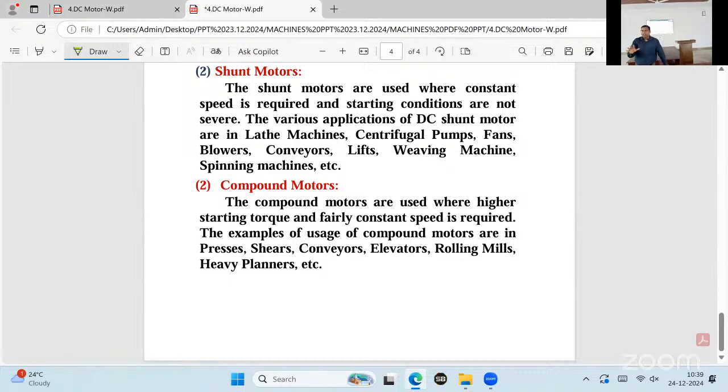For the 10 marks question, what do you have to write down? Definition of a motor, statement, working principle. Then F is equal to B into I into L into sin theta. Fifth one, Fleming's left-hand rule. Application is for a 1 mark or 2 marks question. To get 10 marks, explain the working principle of a DC motor. What will you write for a 10 marks question?